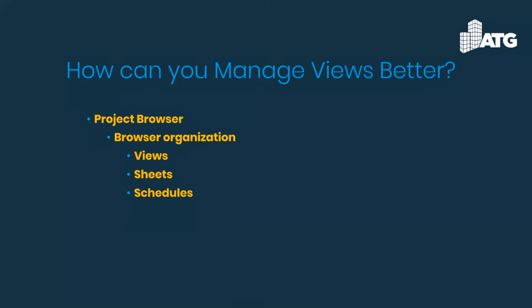So with the project browser, a lot of people don't know, but we do have an option where we can organize the project browser, and we can go in and set this the way that you want to be able to see it. A lot of companies will go in and set up specific browser organization for a project to start. It doesn't mean it has to remain that way. We can go in and change the browser organization depending upon the situation that we're in.